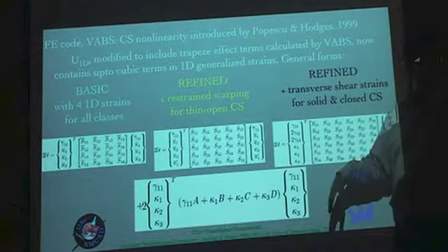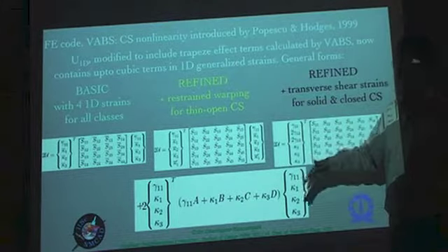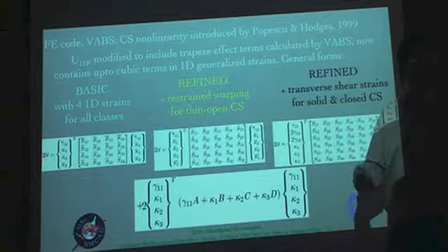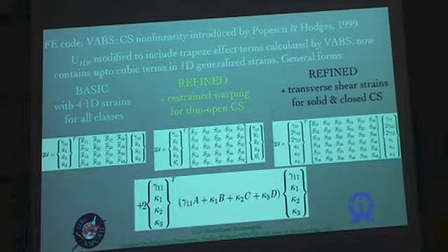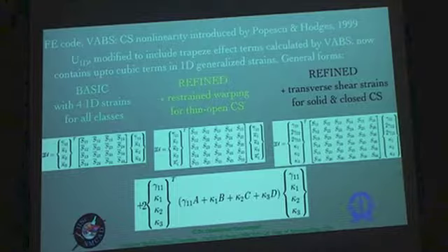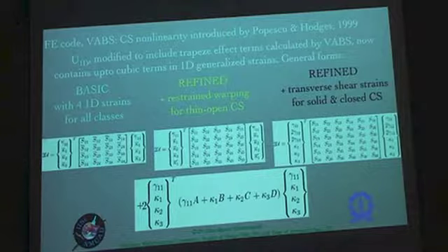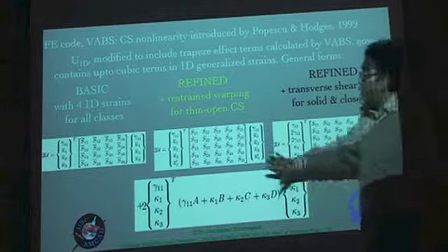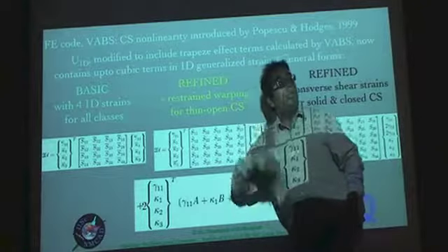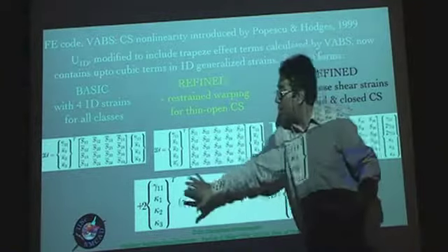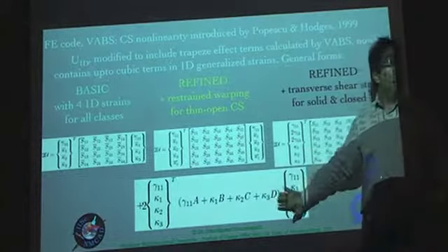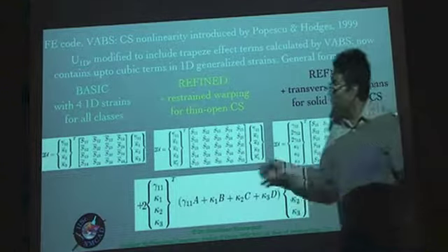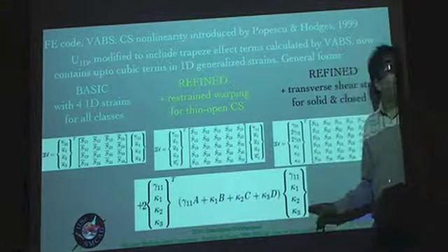Now when we have in specific cases the nonlinear effects becoming important, either because one or more of these curvatures are typically large, either because the torsional stiffness is low or because the bending stiffness in one of the directions is low. In such situations, the variational asymptotic method has to go one step further, and then it has to introduce in the next order of approximation the nonlinear terms.